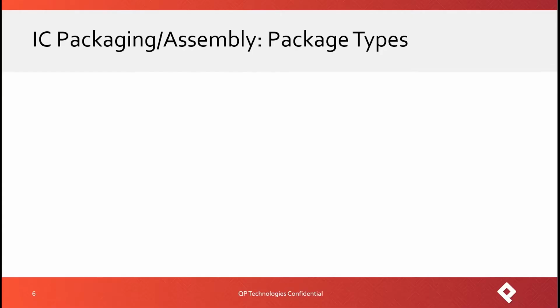I thought I would go through first, I heard some discussion about, gee, what package do I use? I don't know how to approach things. Generally, what I would suggest as a starting spot is two key things. A, how many I/O do you need to bond out? And B, are there any particular performance and physical requirements? From that, there are all sorts of types and variants on a theme.